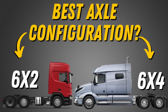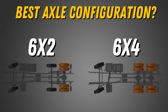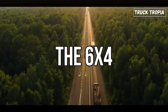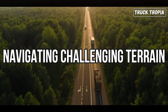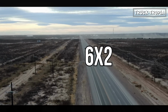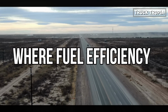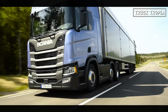The best truck configuration is... The choice between a 6x4 and a 6x2 axle configuration in a semi-truck depends on the specific needs of the operation. The 6x4 configuration is best for hauling heavy loads, navigating challenging terrain and steep inclines, and when traction is a priority. The 6x2 configuration, on the other hand, is ideal for long-haul trucking operations where fuel efficiency, lower maintenance costs, and greater cargo capacity are paramount.